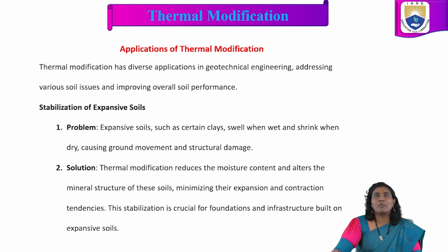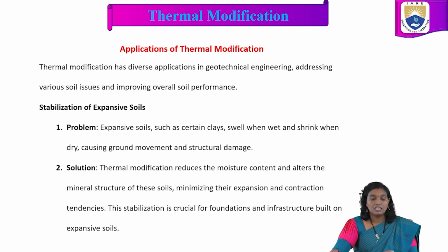Applications. Thermal modification has diverse applications in geotechnical engineering, addressing various soil issues and improving overall soil performance. Stabilization of expansive soils. Expansive soils such as certain clays swell when wet and shrink when dry, causing ground movement and structural damage.